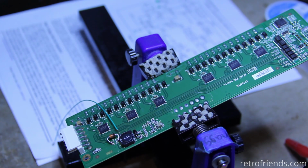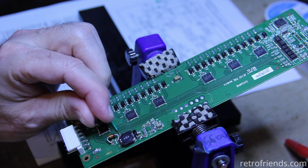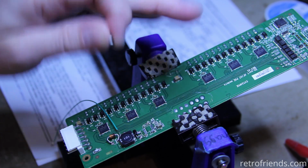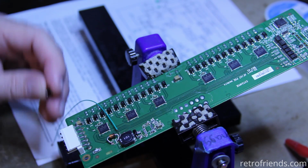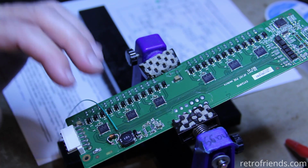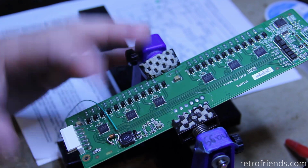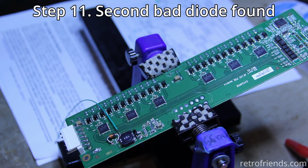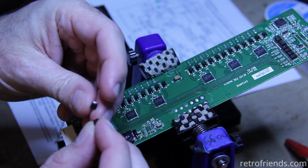And well, long story short, it turns out, even though this Zener diode tested good in circuit, and when I lifted one side off, it was passing electrons one direction but not the other, so it seemed like it was good. But when it was in circuit, there was a 1.5 amp draw, and when I took it out of circuit, the 1.5 amps went down to like 0.1 amps. So that's not a failure mode that I've ever seen a diode make.